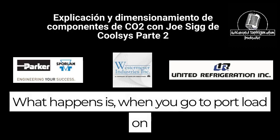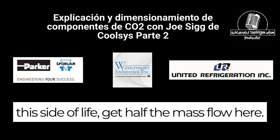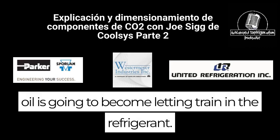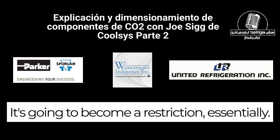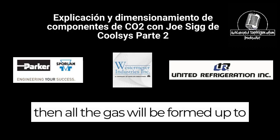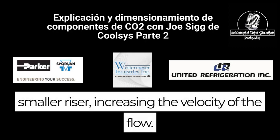What happens is when you go to part load on this side, you're going to get half the mass flow here. It's going to fill this trap with oil because the oil is going to become unentrained in the refrigerant. It's going to become a restriction essentially. Yep, exactly. It'll fill the trap, it'll cause a restriction, and then all the gas will be forced up the smaller riser, increasing the velocity of the flow.